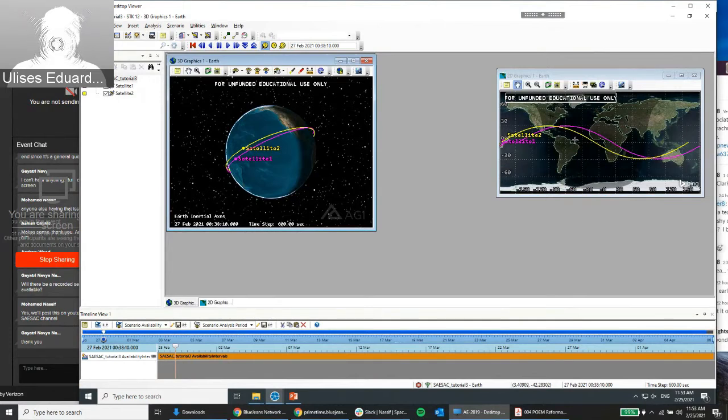This is called the precession of the line of nodes, and this is an effect that we can see very easily, that we can expect, and this is actually something that happens to satellites around the Earth. We can see immediately that the two-body model that we had is really not accurate, even in a couple of days. Just accounting for one more force term, it's already off the rails. But we shouldn't do that.